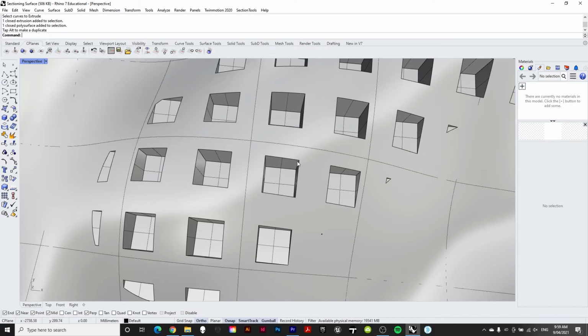So a drill bit is a spinning bit with cutting blades on it for a CNC. Now, because that's circular, what's going to happen is when it goes into here, it's going to leave a radius at the corners because it can only really move in the y-axis and then come again in the x-axis. It can't really go back in and get a sharp corner on there because it doesn't have a sharp edge, it has a rounded edge.